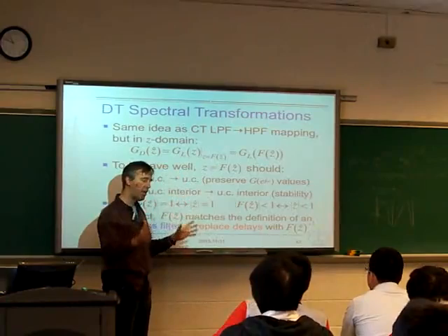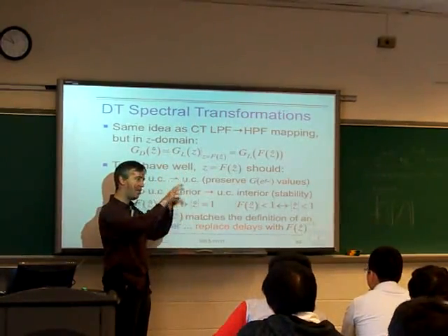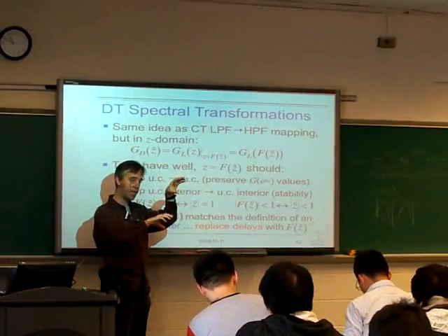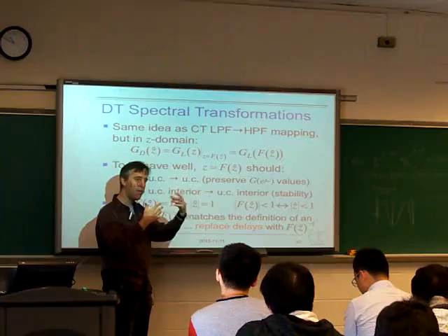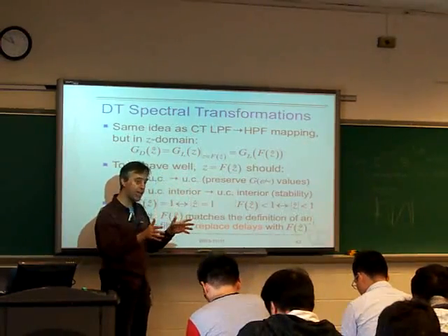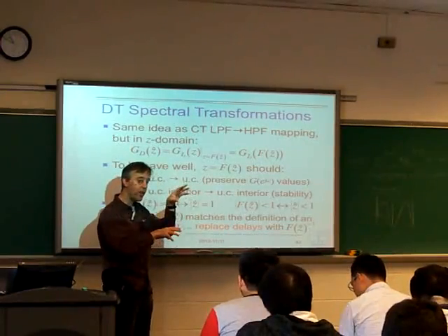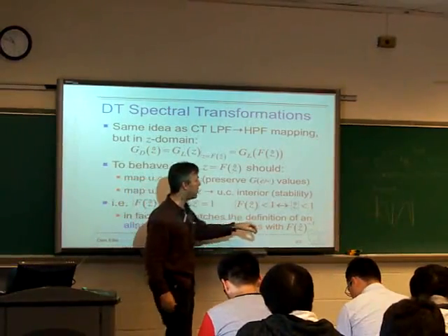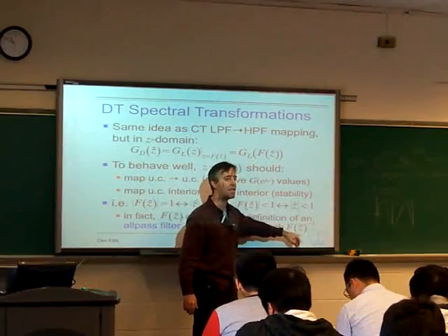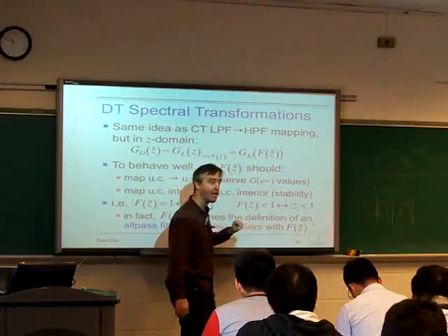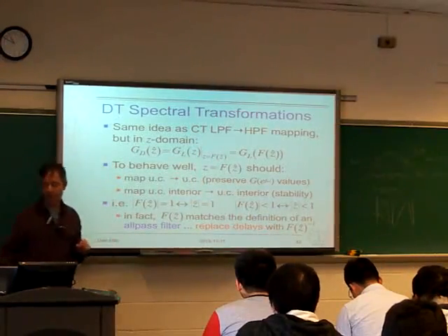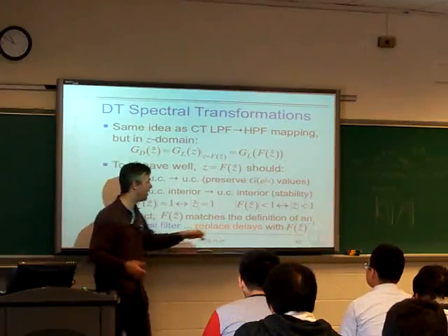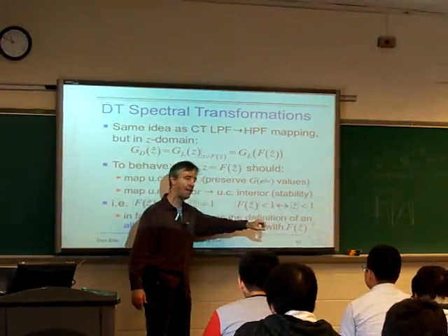If you think about the flow diagram that produces a filter, basically we have a bunch of gains and connections, and then we have these delays, these one-step delays, the z to the minus 1s. And it turns out that we're defining this polynomial by working out this operation as a bunch of individual applications of z to the minus 1. So if we just take each of those delays and replace them by this all-pass filter structure, we end up building this discrete time warped filter. It's not that useful because the warps you do here are typically quite limited.